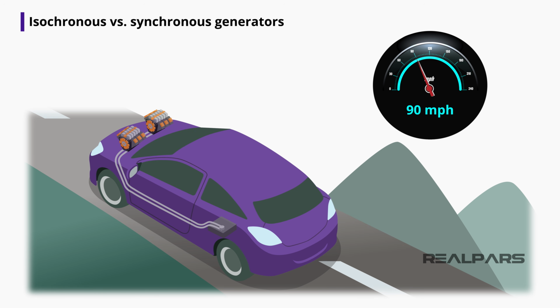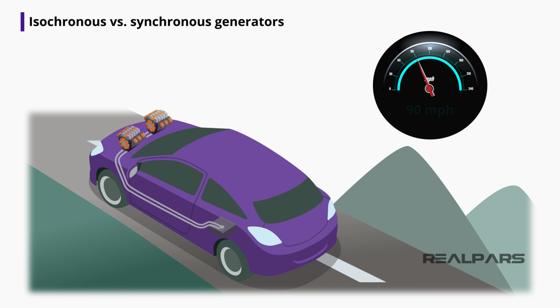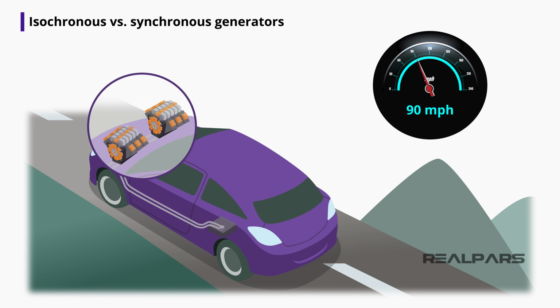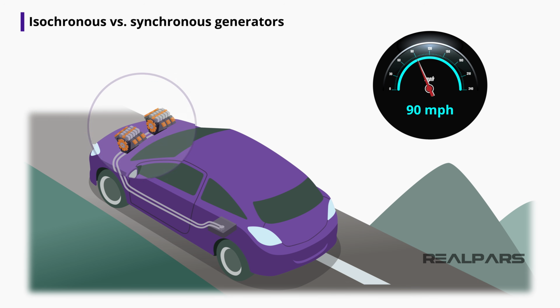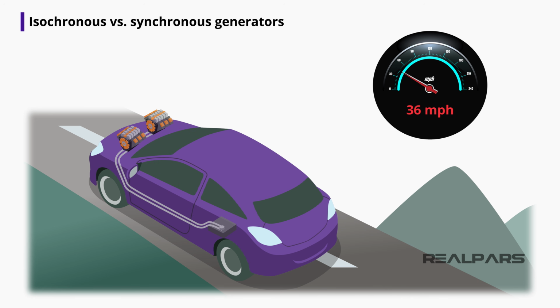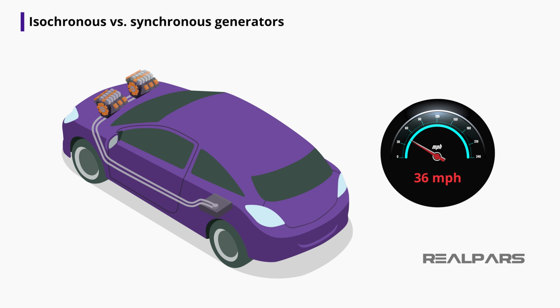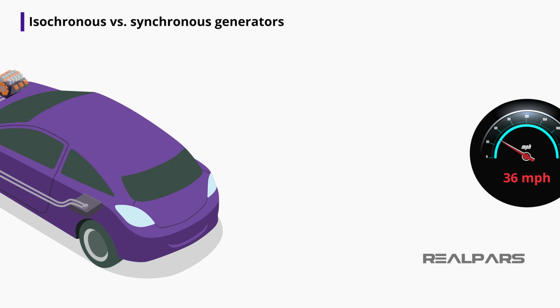So instead of reaching that speed, you overshoot and go even faster. Now, the error is on the negative side, and again both engines and control systems are trying to respond to that error and would slow down too much, and so forth. This would cause a constant instability of both engines fighting each other, and you would never be able to reach the 60 miles per hour as needed.